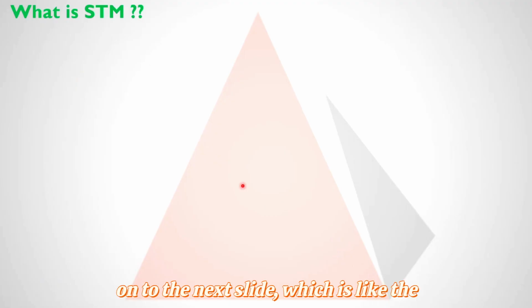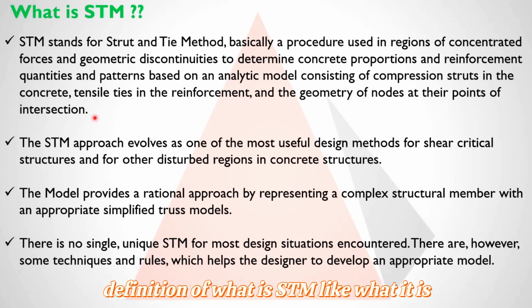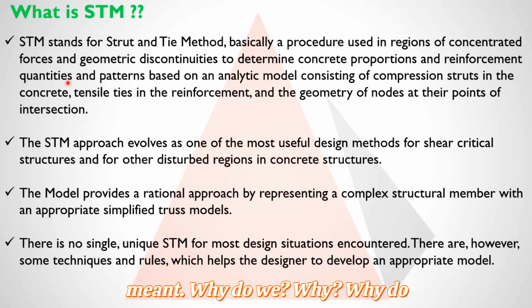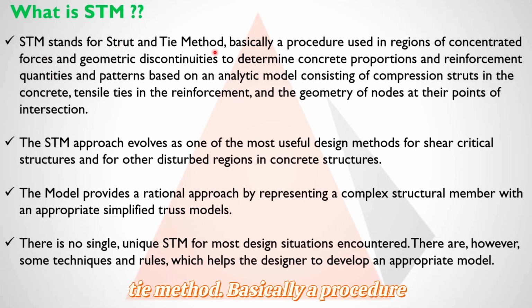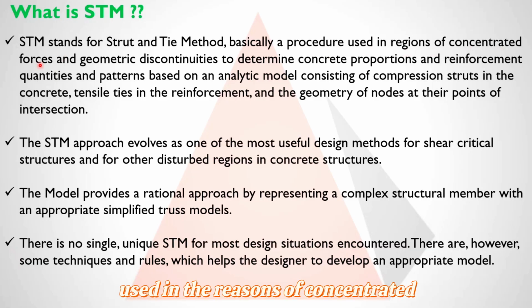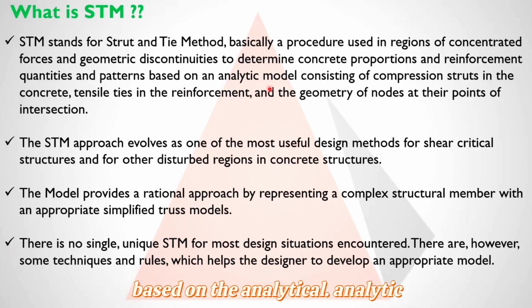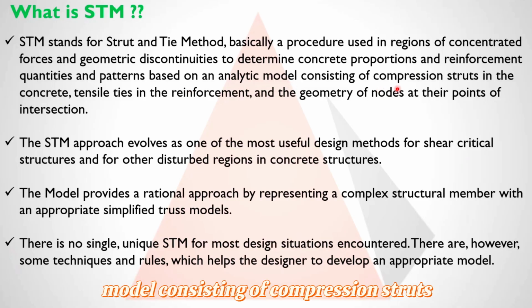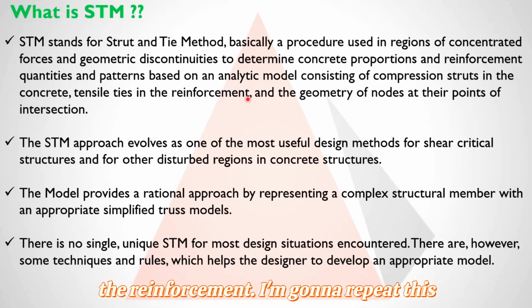Now coming to the next slide, which is the basic and very first definition of what STM is, what it means. Why do we do this? STM stands for Strut-and-Tie Method, basically a procedure used in regions of concentrated forces and geometric discontinuities to determine concrete proportions and reinforcement quantities and patterns based on an analytic model consisting of compression struts in the concrete and tensile ties in the reinforcement.